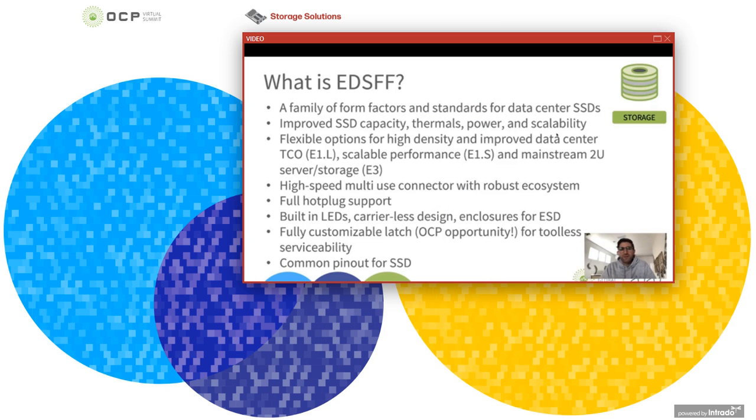So what is EDSFF? EDSFF is a family of form factors and standards for data center SSDs. It's been developed really to improve capacity, thermals, power, and scalability, addressing all the challenges that previous SSD form factors had because they weren't designed natively for SSDs. Just like with NVMe, we got a brand new fresh start on an SSD protocol and spec that wasn't designed for hard drives and rotating media. So EDSFF is kind of like the NVMe for form factors.